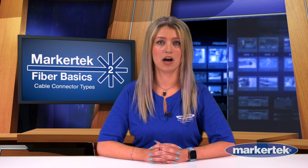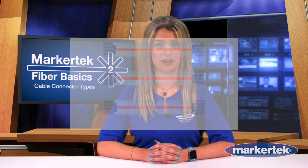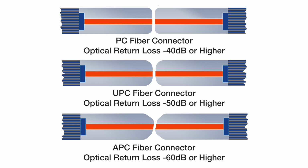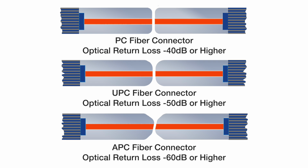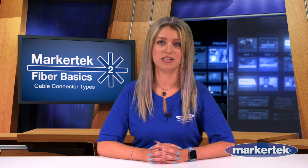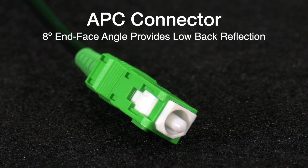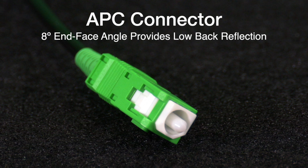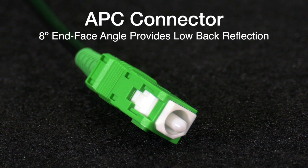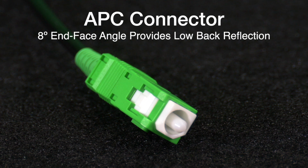In the evolution of higher bandwidth applications utilizing fiber, like RF video and broadband, return loss, which is a measurement of the light reflected back to the source at an optical interface, needed to be reduced. The way to accomplish this is by cutting the fiber end face diagonally. This is known as APC, and APC connectors are green. You cannot mate UPC and APC connections. The color of your patch cable ends should always match the color of the chassis mount connectors and cable couplers.